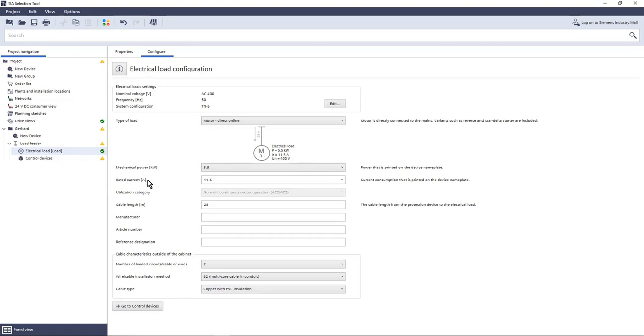The first motor we have in the sketch right now is a 5 kilowatt motor. We go with a 5.5, of course, because we have to go over it. And as you can see here, the rated current is automatically calculated because of the standards that we have. This tool, as you remember, is called the IEC one. So this is based on the IEC standards, okay?